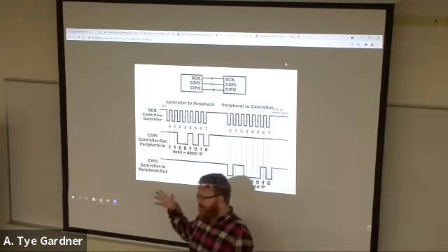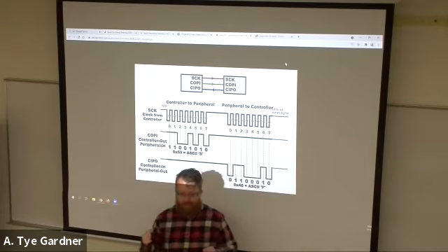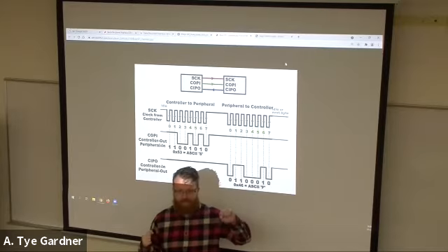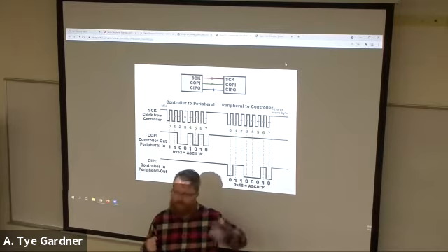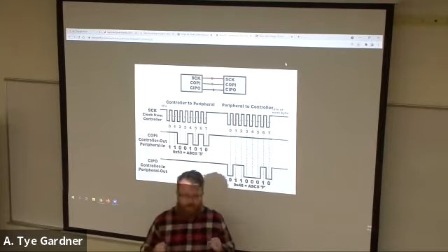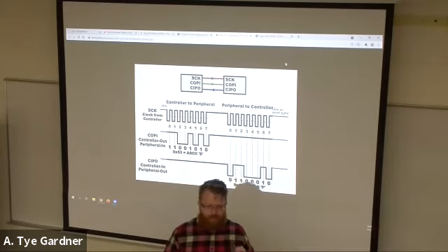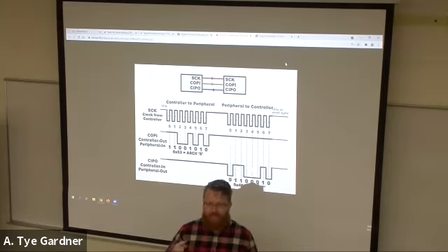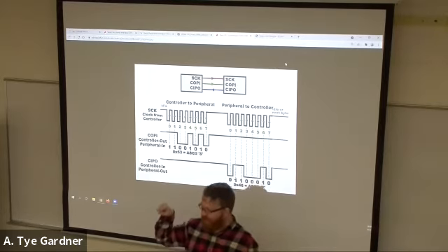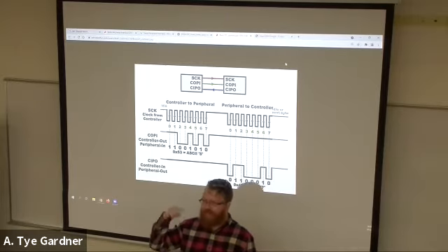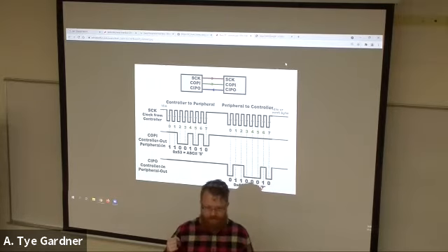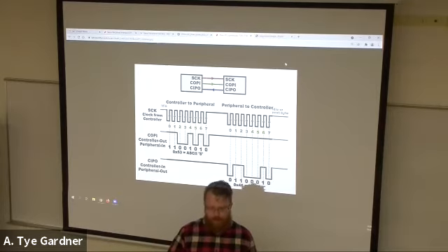Now, we do teach ways that you can do clock recovery. Actually, I'm trying to think, I think they teach it in digital communication now. There's a thing called phase lock loops that can be used to build a clock recovery circuit that, as long as you have enough alternations between 0 and 1, it can calculate your clock speed. And even if there's drift, it can update. That is used for asynchronous protocols.